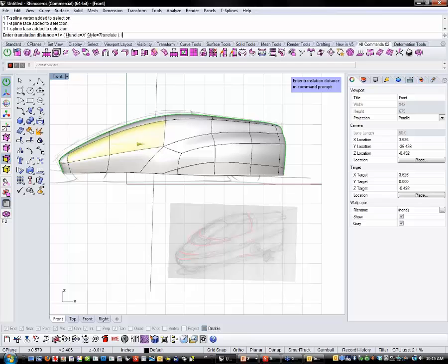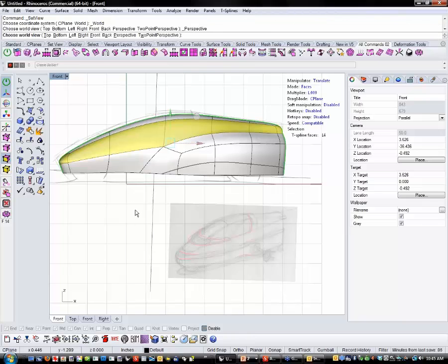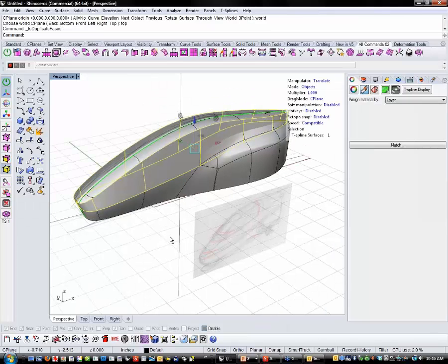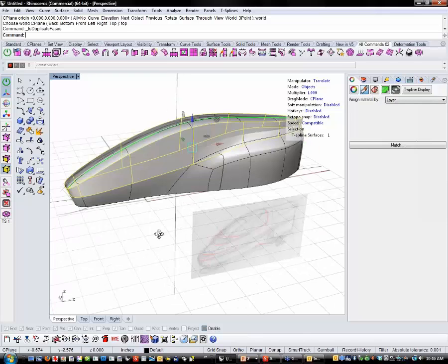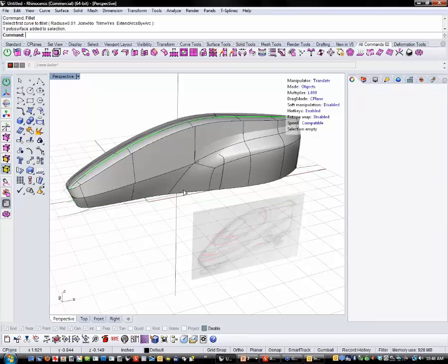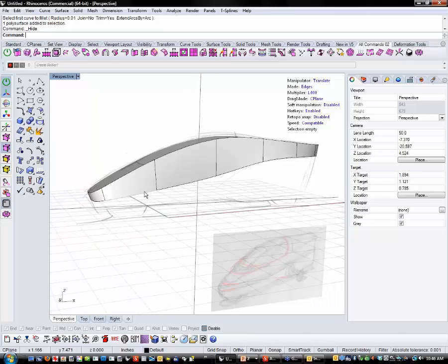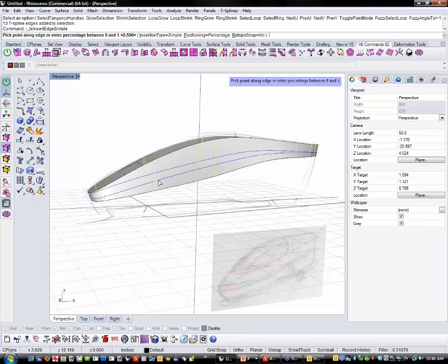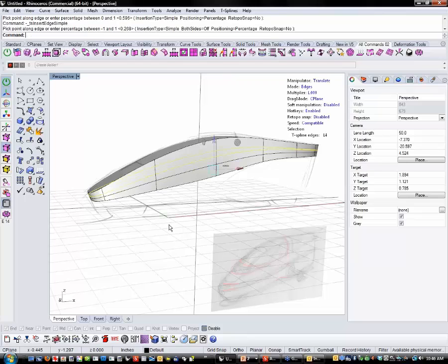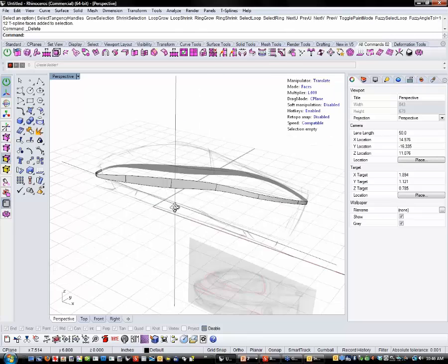So I'm going to go ahead and just select all of those like that. And I've got a row of edges around there. Well, what if I just were to duplicate those off and look at just that? Let me see if I can hide this for now. All right, so let's just look at this for the time being. Well, what can I do with that? I can add an edge here to get this to be thinner, right? And then I can pick these faces up here and delete them, and now I've got a little thin strip, right?